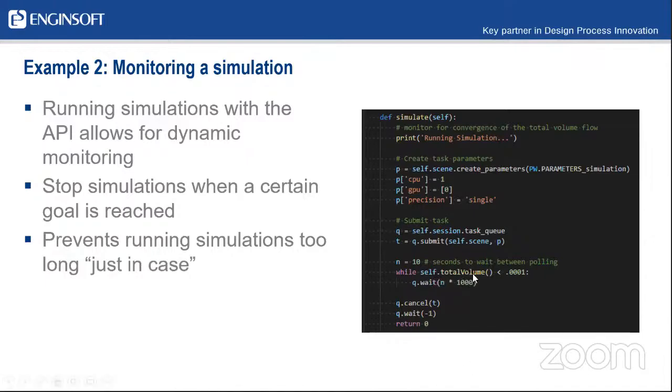So in this case, the example I'm using is using a pandas library, and you'll see this in the full code. But on each of those outflows, there's an outflow dash name of the object. And that's a CSV file that gets kicked out whenever fluid is escaping an outflow. So by using code, we can parse through all of those every couple of seconds and then add up the total amount of fluid that has come out of those holes. And once we achieve some target, then we can stop the simulation.